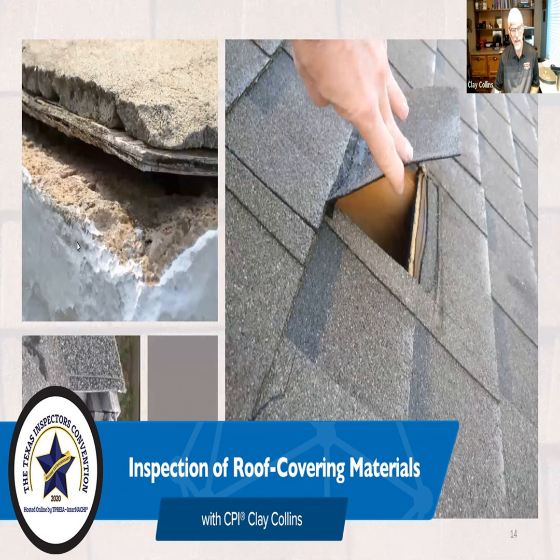You could have a little bit of leak by that boot because it doesn't look like that boot was installed shingle flashing as shingle. It looks like the apron of that boot is underneath the shingles. Kind of hard to tell from here, but that's what it looks like, which means all of the additional mastic that they put here, or sealant, may not have been necessary.